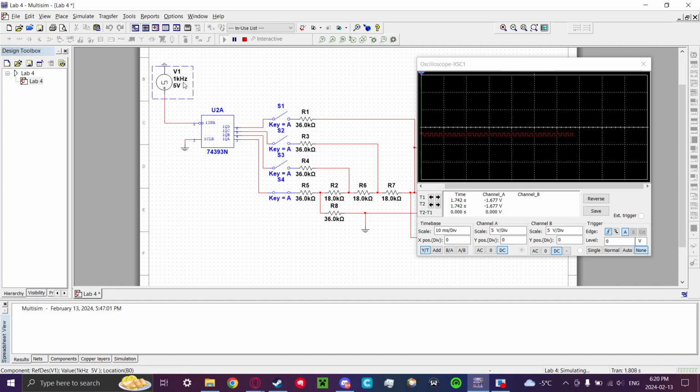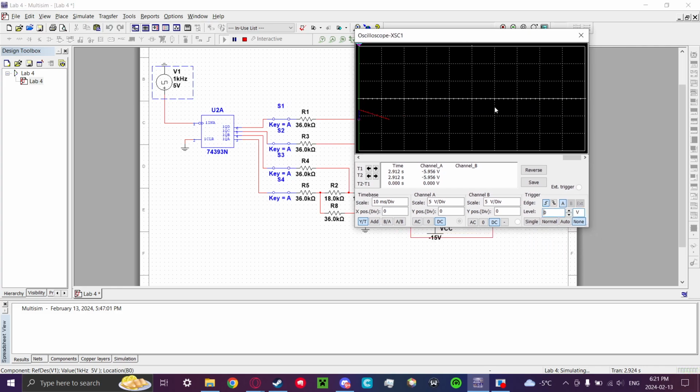So it looks like using the square waveform here through the binary counter, this bottom input is the first digit in binary, and then going upwards, the next digit is in binary. And so when you put, say, 1 and 2 together, it makes a small slope, and the more you put on, more values are coming through from the binary counter. It makes a larger slope of the number that's being output.